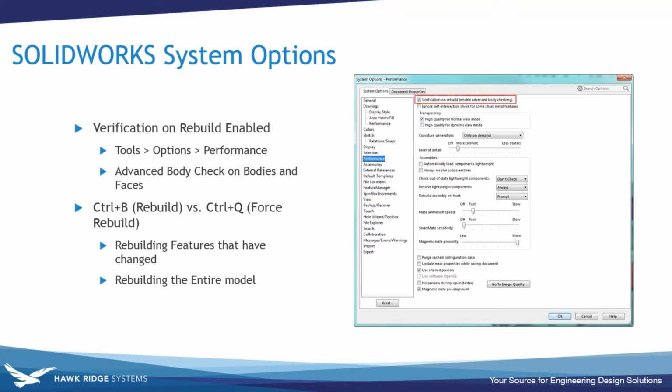there have been situations where you are modeling or creating an assembly with that option off, and you may have edited or changed some element of the component, and a normal rebuild just didn't catch it. A normal rebuild just didn't catch the change, and in reality, you may have broken a mate, you may have broken some sort of reference, where a normal rebuild is just going to refresh the changes, but sometimes may not catch how that change is going to affect the overall model.